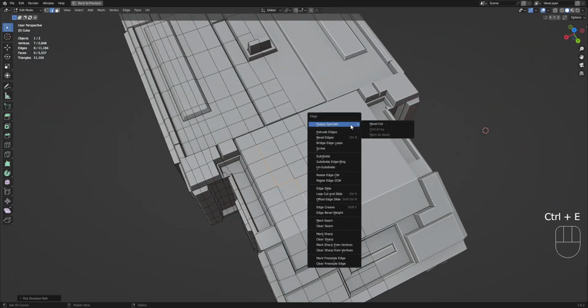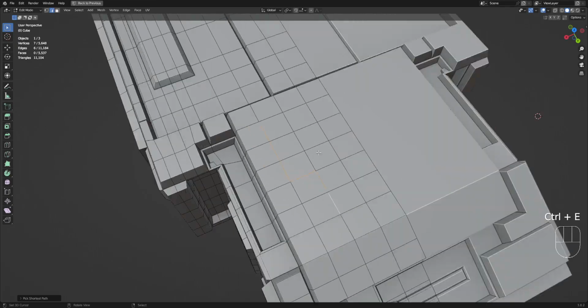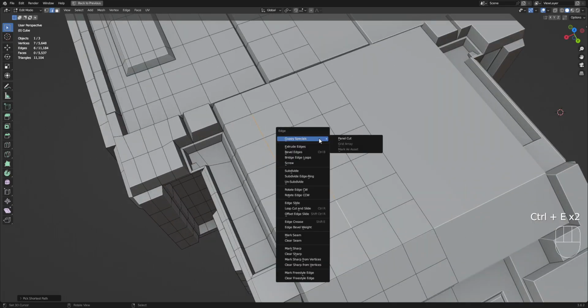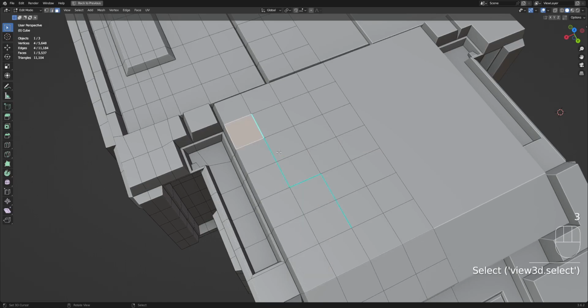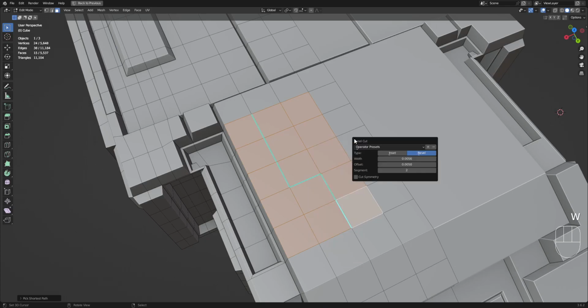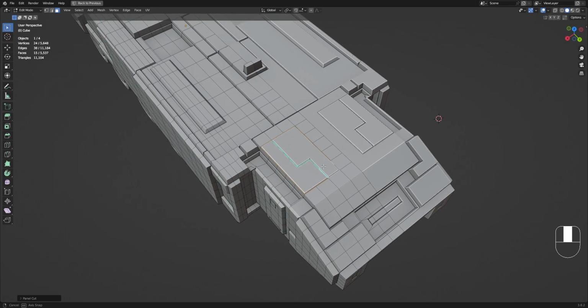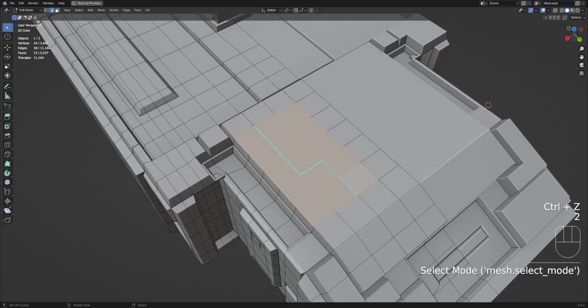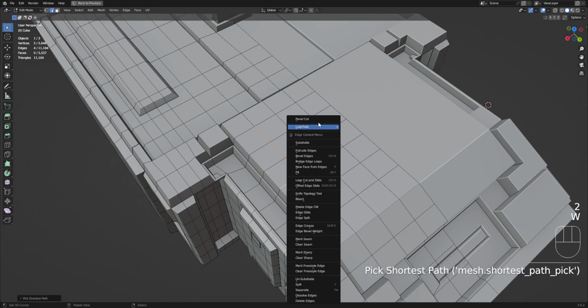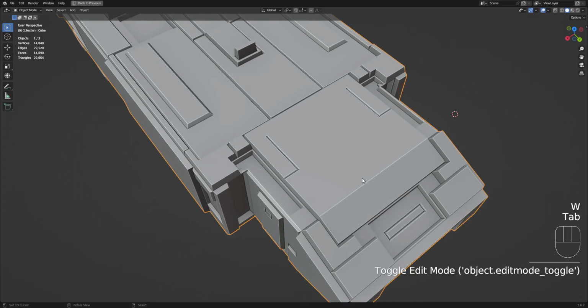But of course, the default algorithm, what is the inset type, you need to mark sharp the edges and then select the faces that include those marked sharp edges, then use panel cut and then use the offset. Then you generate the panel cut detail. But with the inclusion of the bevel type in the next update, you can just select the edges, then use bevel type like that.